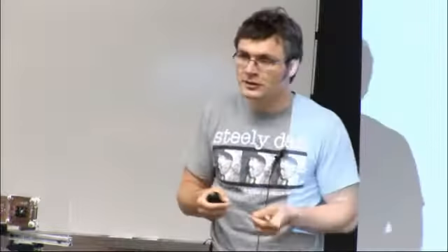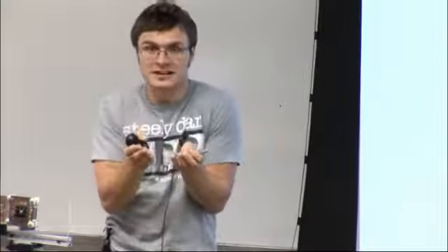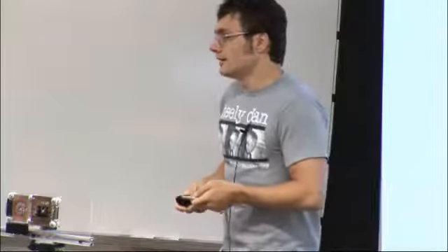If you have more than one microphone or more than one loudspeaker, even if each microphone is omnidirectional, you can achieve an overall directivity of the system that is selective, by properly playing with the signals that you record from these microphones. We can use this to create a beam of sound or to listen in a beam of sound, and steer this beam electronically, by changing the way you play with these signals, and scan the scene.